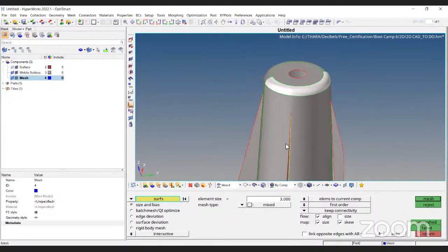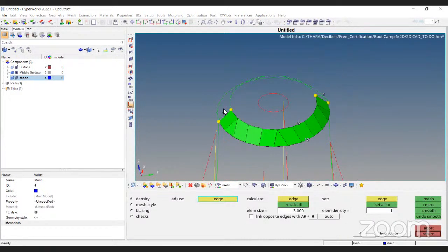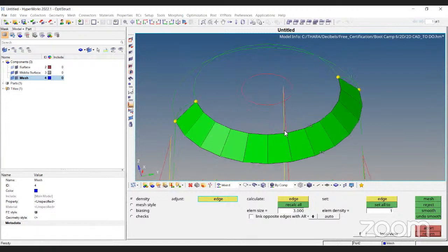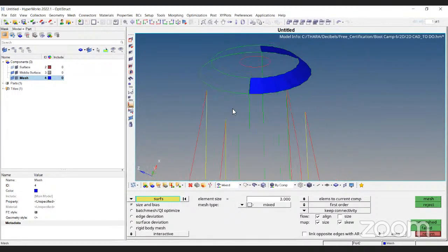First you choose the surface, say mesh. See, keep it in a skeleton view. See, this is how it looks. If you want, you can increase. If I'm decreasing one density, see one tria is there. Why? Because there is a mismatch in the density. There is a mismatch in the number of nodes. So it is going to have one tria. So if you make the same nodes, the tria will go. So like this, you need to mesh it.